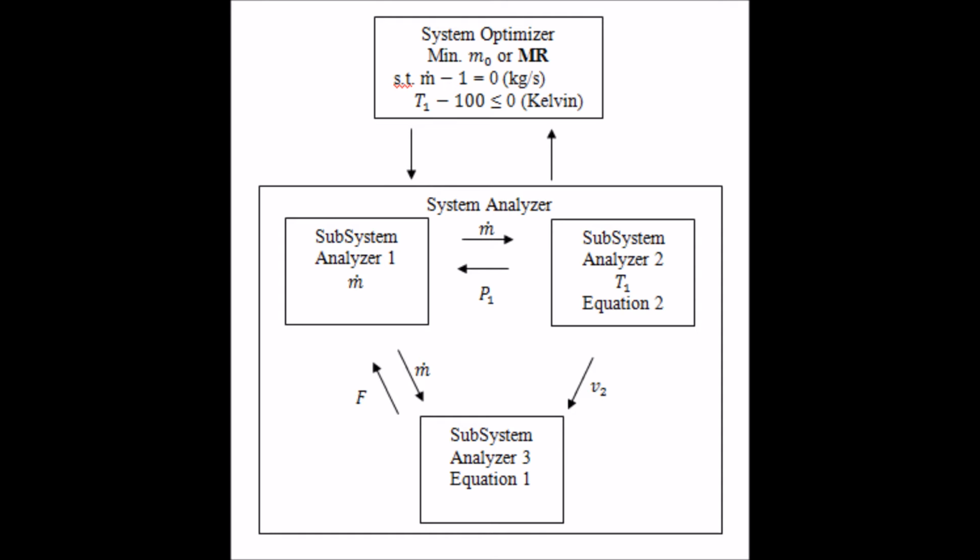The purpose is to minimize the initial mass while maintaining the propellant mass constant, allowing a lighter, more compact vehicle. With a lower initial mass, the closer the mass ratio will be to 1.00. This is determined with respect to the given mass flow rate. Once the system fully converges, the iteration process was repeated multiple times while varying chamber temperature and keeping flow rate consistent. Obtaining enough data points on this level can lead to the capability of using a one-dimensional optimization tool.